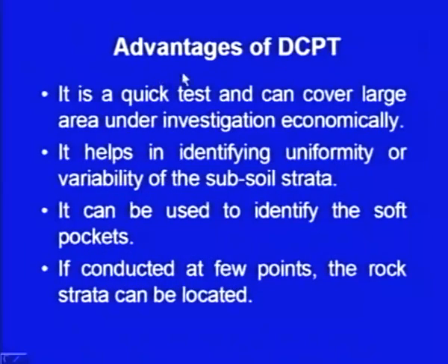The advantages of DCPT: it is a quick test. We do not have to do boring; we have to attach a cone and then just keep on hammering it, keep on counting the number of blows. So, it is a quick test. Economy wise, it is a cheaper test, quite cheaper as compared to SPT, and it can cover a large area under investigation economically. So, if you are working on a very large area, then this test will be very advantageous.